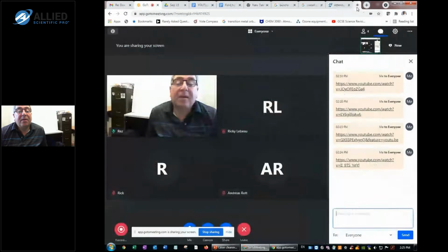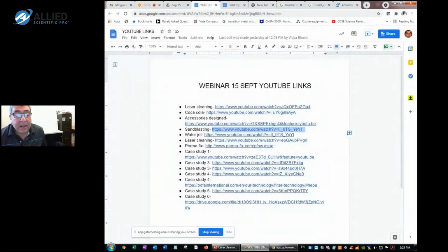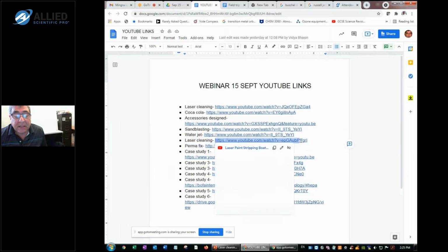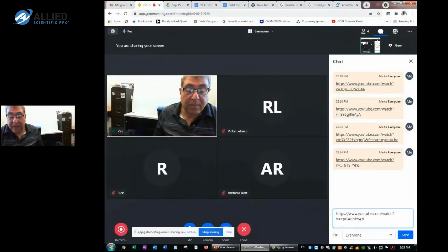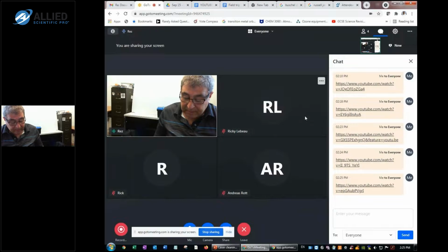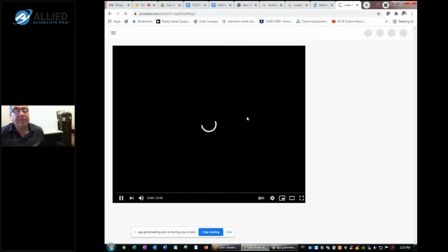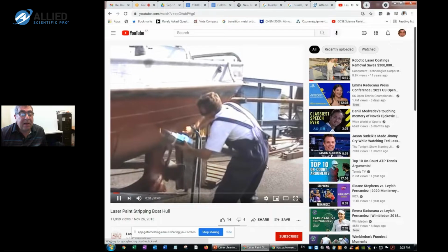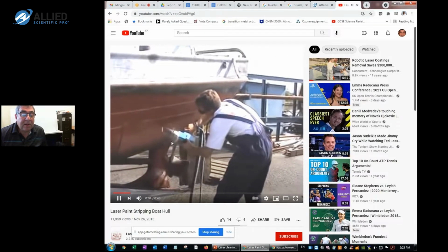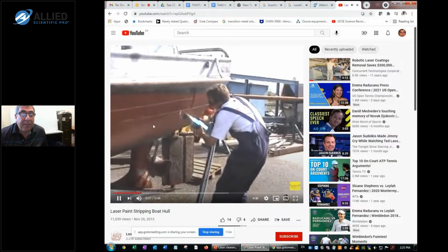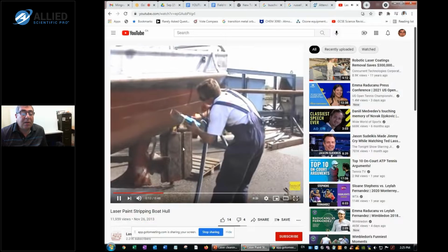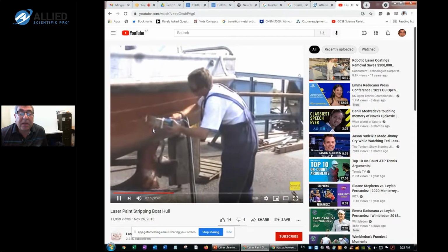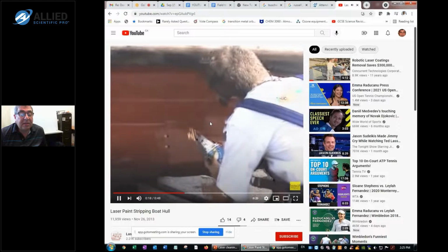On the other hand, you would also have the laser cleaning method. I'll send you the link. I won't show the water cleaning because it's kind of similar to sandblasting. So I'll send you that and I'll also play it. And you can see here it's much neater. The laser cleaners keep cleaning the body of the ship, and this thick tube here is removing all the debris on the spot, so none of the contaminants is going into the environment.